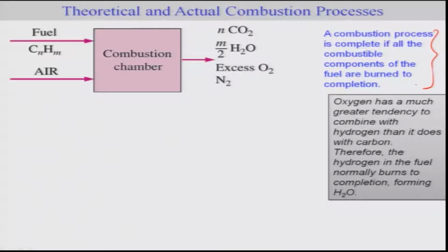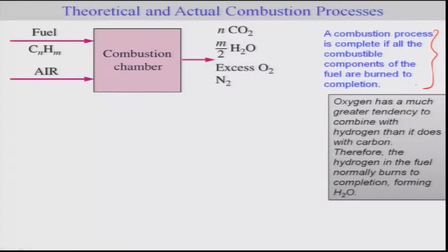Many times you may have to provide a little more because you may not know exactly the contents of the fuels, or you would like to be absolutely sure that the fuel is burned. So hence we need to add more oxidizer or air in order to have complete combustion. So there is a theoretical limit. We call it theoretical air percentage. So let me just go through that.